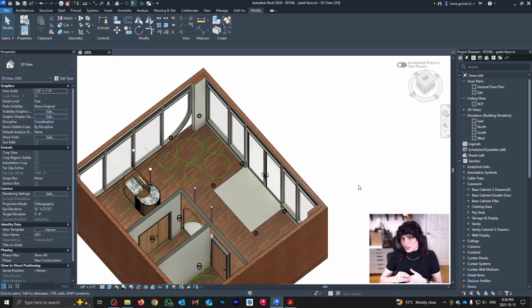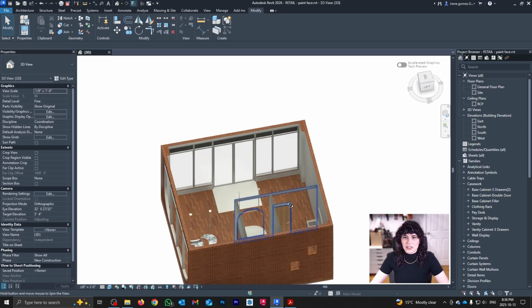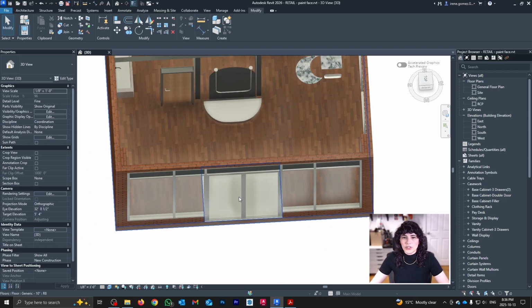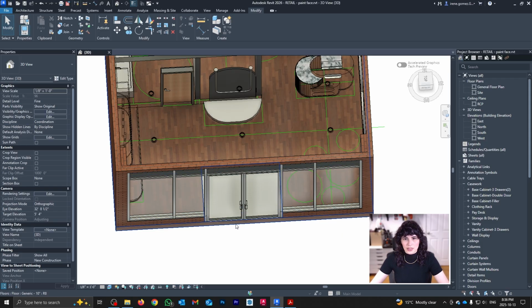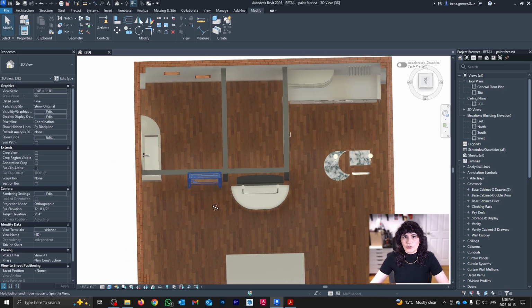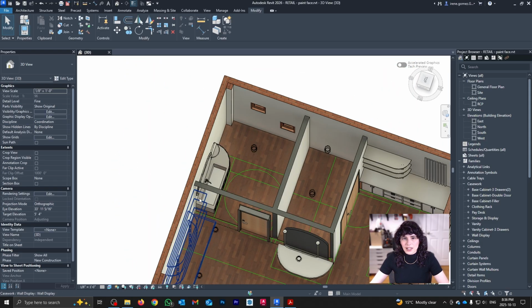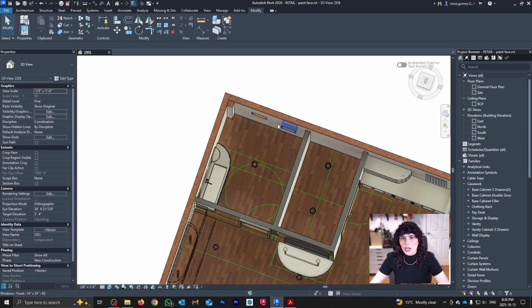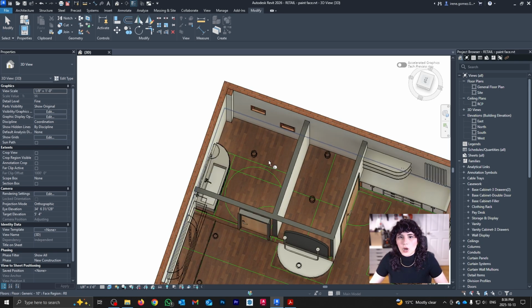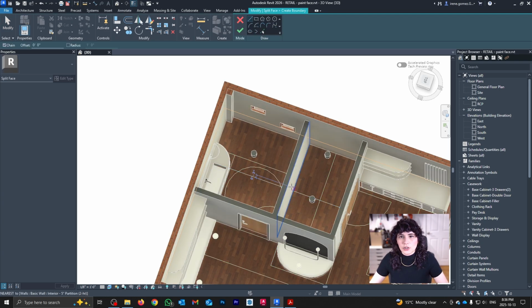Now, the other way that you can do it is by creating a completely independent, separate boundary. What do I mean by that? Well, this boundary here was starting and ending at the orange line. But for example, here for my floor, let's say that I just want to create a rectangle taking into account my existing walls. Same thing, I'm going to go SF for split face, and I'm going to click on my top surface again.